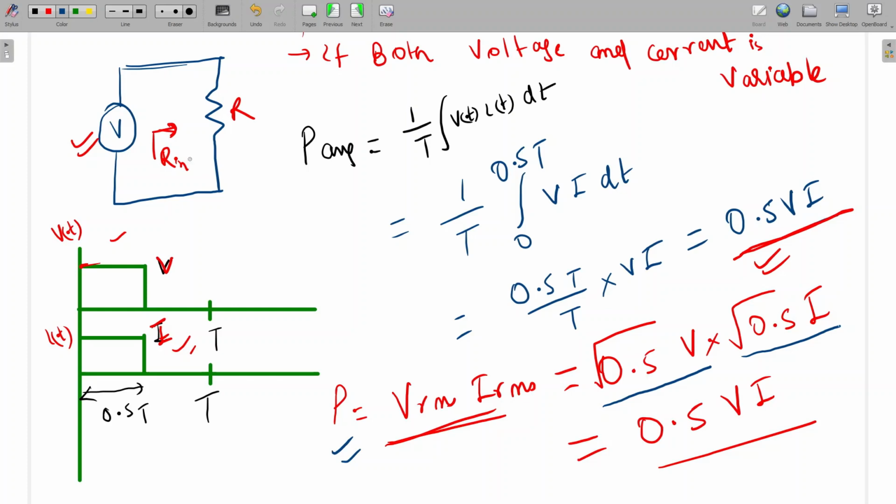See, this is the fundamental average power formula. This I am only applying everywhere. But if one value is constant, we take that outside, meaning for the other value we take the average. If both values are variable, in that case, for power we have to multiply VRMS into IRMS. Is it clear? Is it clear to all? As variable, they are functions of time.